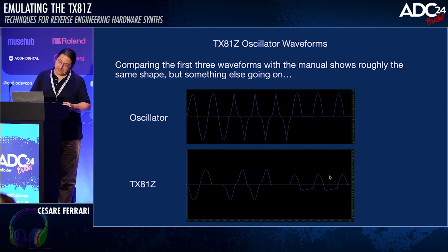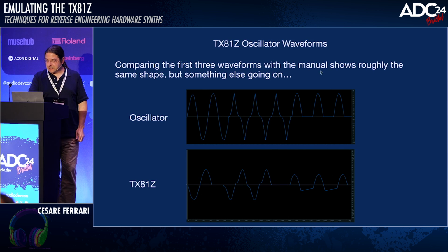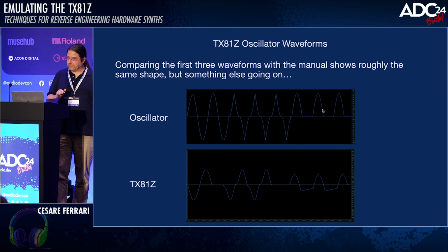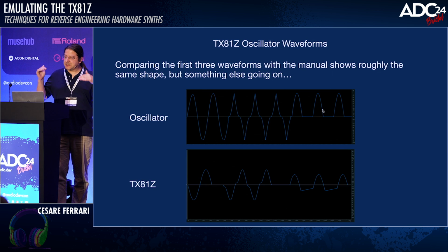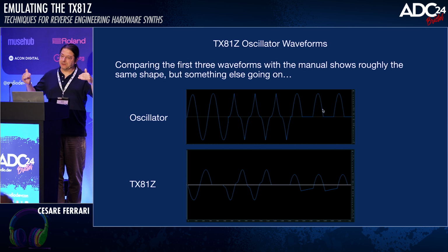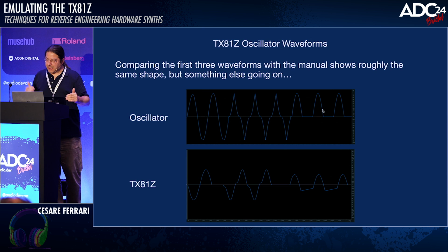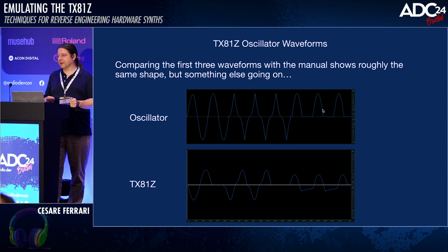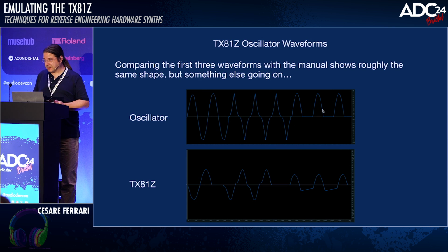Now again, this is fairly obvious if you think about it. What we're doing at the top here is creating a massive DC offset. We're doing the positive half of the waveform and then zeros. So there's a DC component here. The average signal is not 0. This will upset amplifiers and burn out voice coils and speakers. This is not something you ship. You don't want your synth to do this.